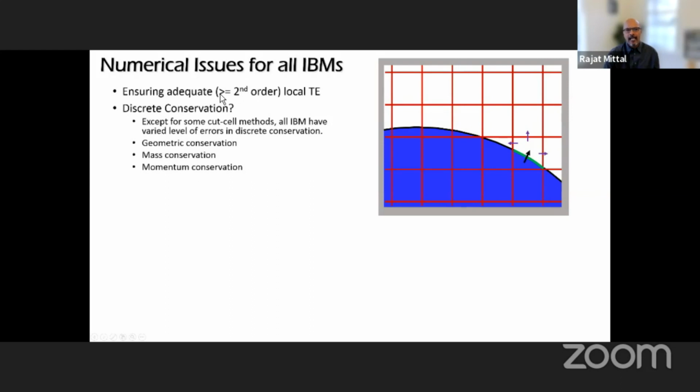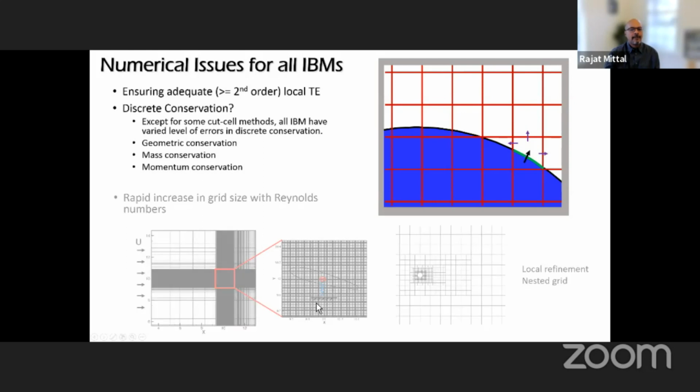And when we say adequate accuracy, anything better than second order accurate is considered good enough. A second order accurate code, which is locally and globally second order accurate, can give you very, very good results. This has been shown again and again. In fact, the vast majority of commercial codes and even research quality codes, finite difference or finite element, tend to be at most second order accurate. So that's a very good aim to shoot for.